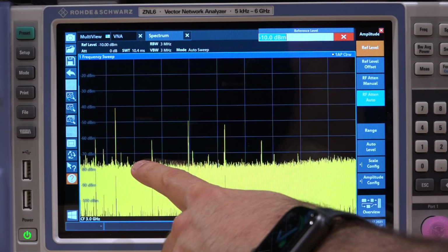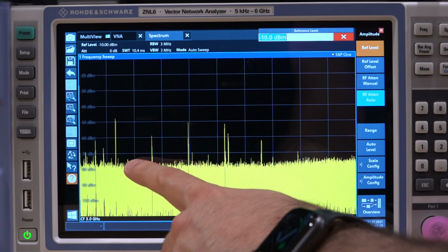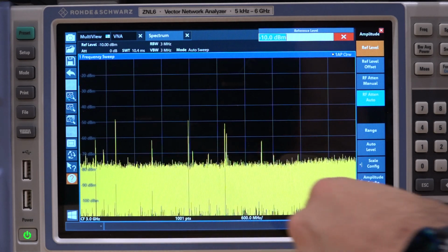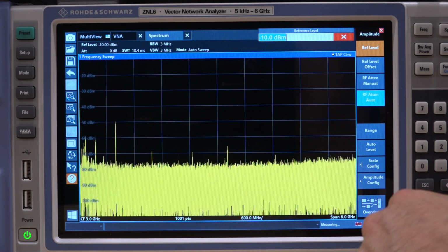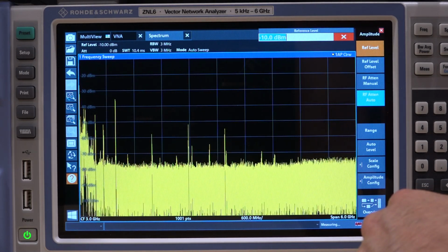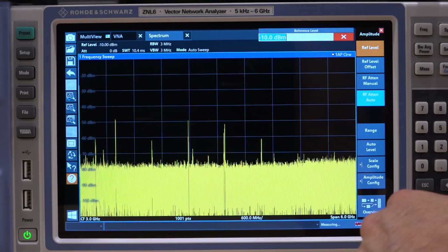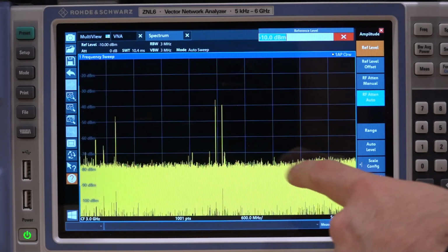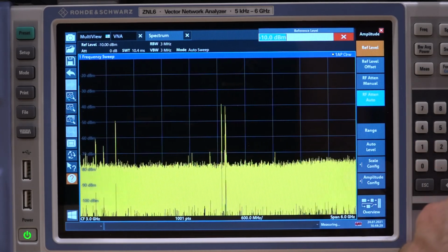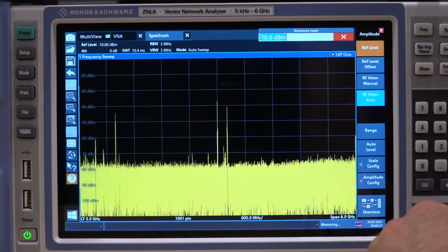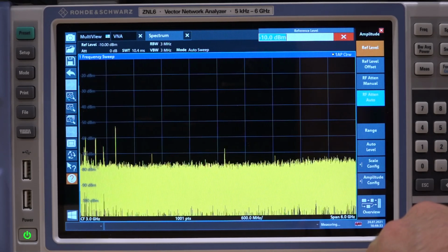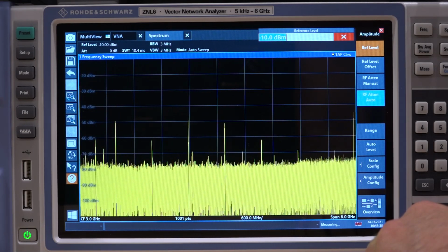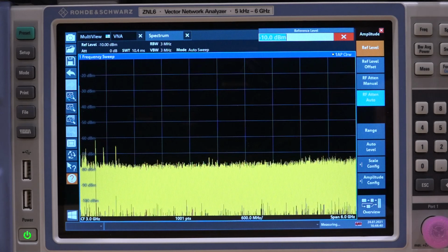If this divider was dividing correctly, you would see a signal jumping around, correlated with this one, at 1/4 of the frequency. But there's absolutely nothing there. Either I'm probing it incorrectly or something is wrong. Interesting. I'm going to have to investigate this a little bit further. Here's the input again. You can see it jumping around. Again, this probe has a huge attenuation, so don't look at the numbers on the left side of the axis. Let's see, going to the output once again. Yeah, it's not there.